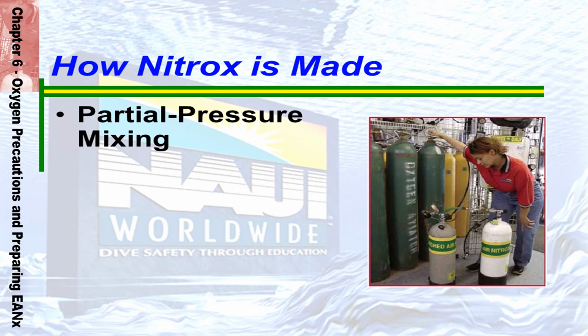Partial pressure mixing systems are the easiest to set up, requiring only a source of high-pressure oxygen and a source of clean high-pressure air. The air used for nitrox blending must meet the higher standard of purity with a lower hydrocarbon level than ordinary scuba air.